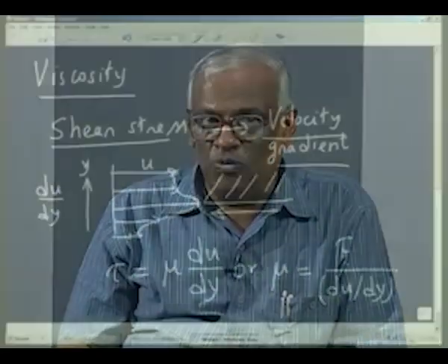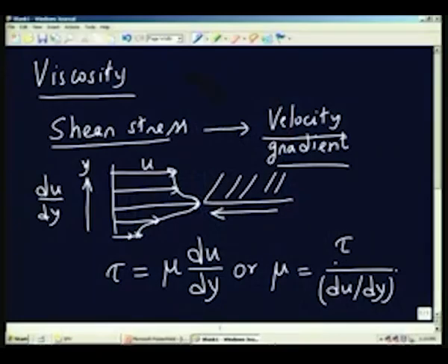In the case of tube flow, the effect of the shear stress or the shear at the wall is to give rise to a pressure gradient in the direction of flow. So the pressure reduces in the direction of flow, and the pressure can be easily measured because it is a scalar quantity, and we already know how to measure pressure by attaching a manometer through a static hole. We can provide static holes along the length of the tube, connect a manometer and measure the pressure drop very easily.